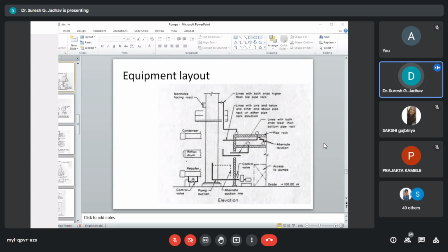This will minimize the interference of the piping. Most reboilers are at grade next to the tower with a centerline elevation that is 1.5 to 2 meters above ground. This is to facilitate tube bundle removal and maintenance access to valves and instruments. In this arrangement, static head is well determined between the exchanger center line and the draw off and return nozzles on the tower.